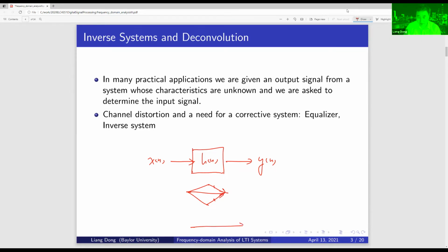So looking at this H[n] in the time domain, we have an impulse here, which is the first impinging wave. Then we have some delay effect. These are due to those two multipaths. So in the time domain with those delay effects, I have not only H0, but I have H1, for instance, and H3, for example. H2 is 0 here.